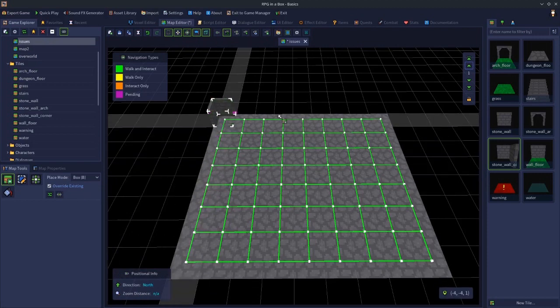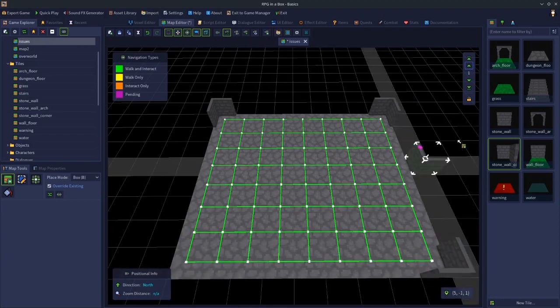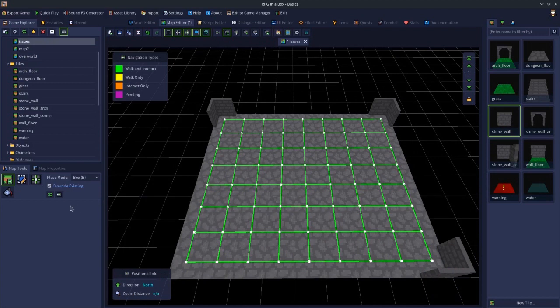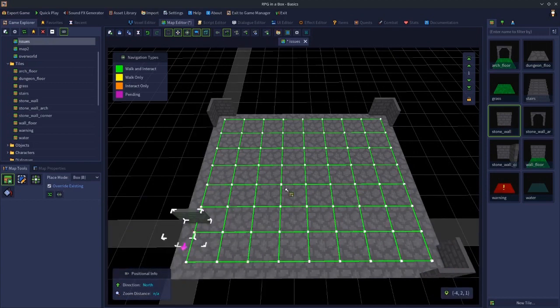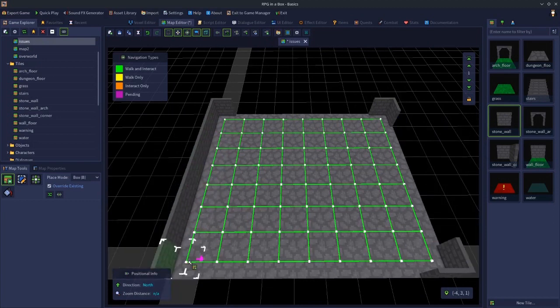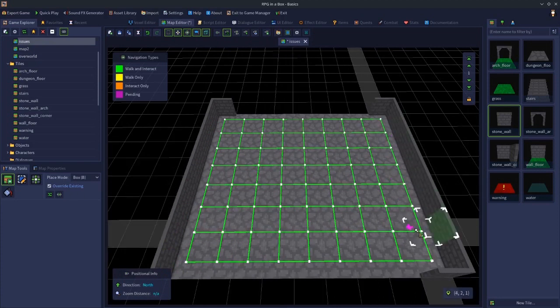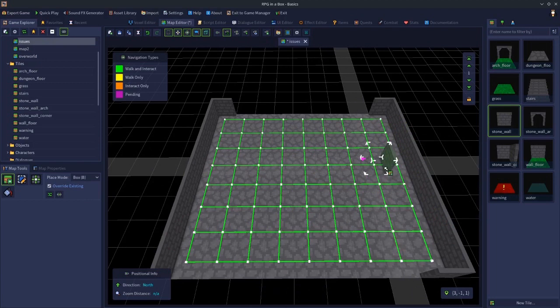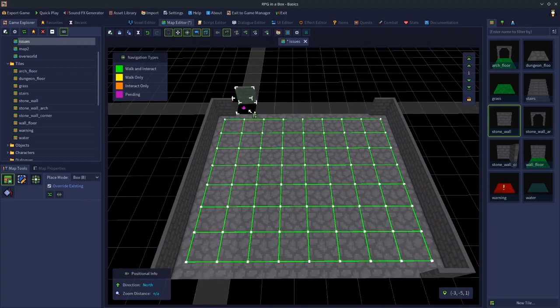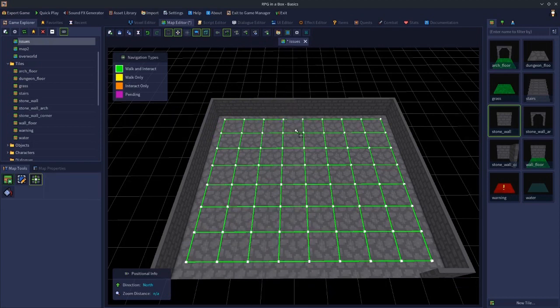So now if we click, click, click, and click, and then we can do the same with our wall. Make sure that's off. The corner one didn't get placed for whatever reason, but you can see, you get the idea. You just drag these around with this off. And it won't delete the lines, so therefore you won't have to put them back, and then you won't run into the mistake of putting them on the wall. But now because we drew the lines before the walls existed, the lines therefore aren't touching any of the walls. So that's one way you could do that.